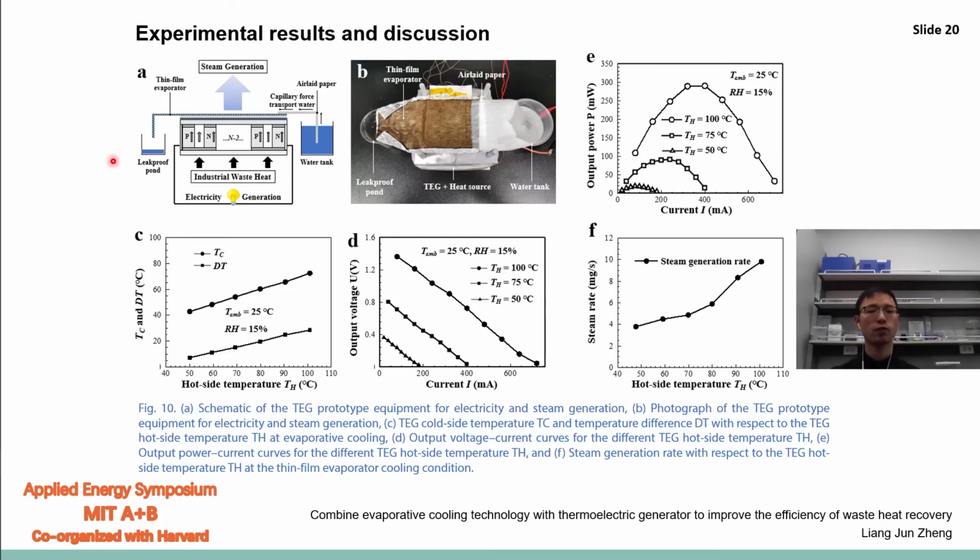So here, we want to utilize capillary force to replace the syringe pump. We utilize air-laid paper attached to the cold side of the TEG, and by capillary force, the water can be effectively pumped to the cold side of the TEG.